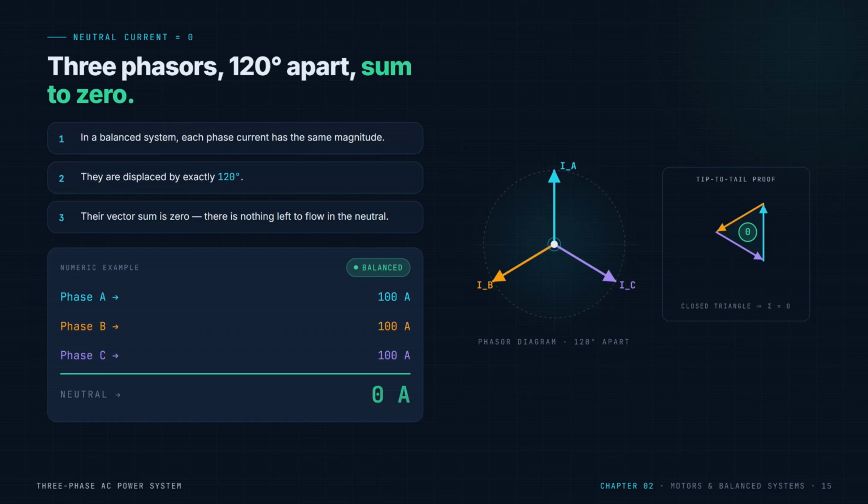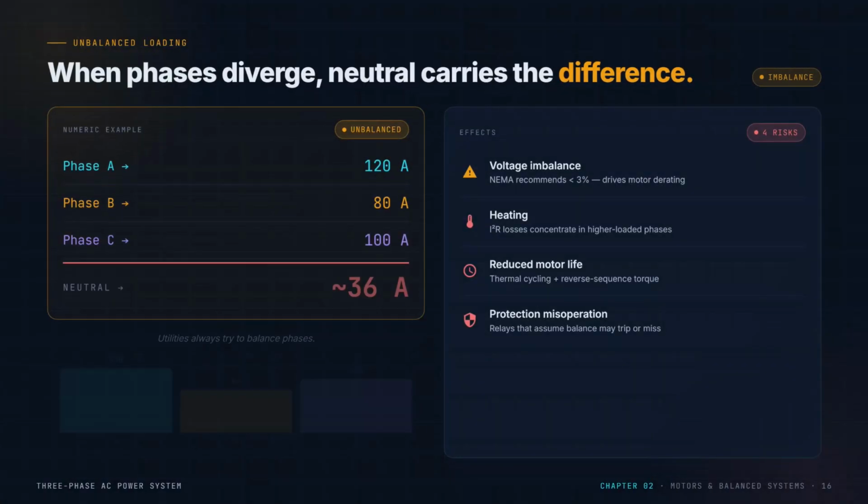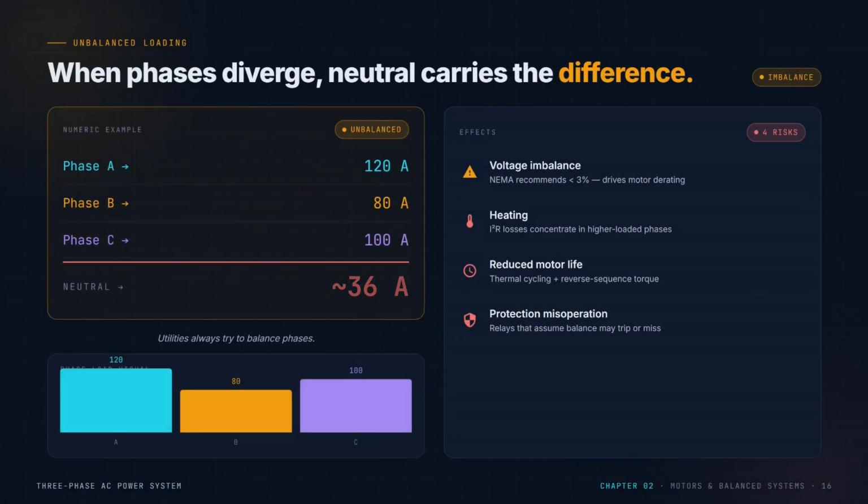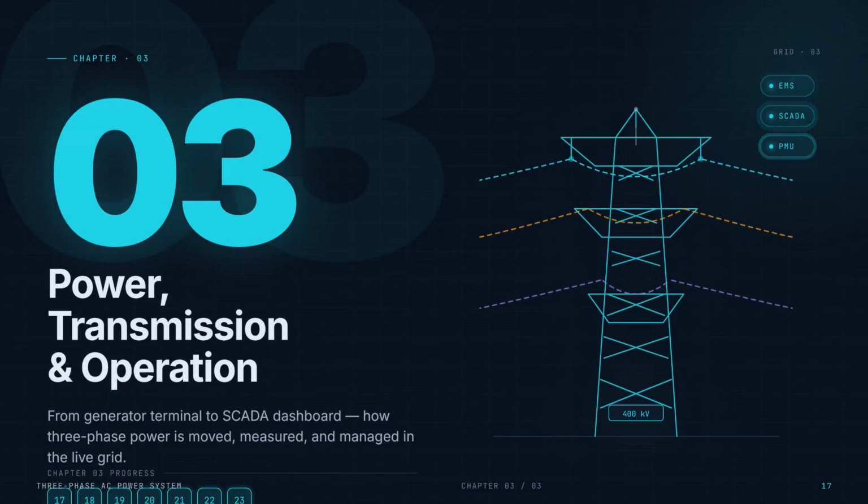A single-phase motor produces an alternating magnetic field that simply oscillates back and forth, creating no preferred direction of rotation. Consequently, single-phase motors require additional starting windings or capacitors to begin rotating. In contrast, a three-phase motor immediately develops a rotating magnetic field as soon as power is applied, producing starting torque without additional components. This results in simpler construction, higher efficiency, lower maintenance requirements, smoother operation, and longer service life.